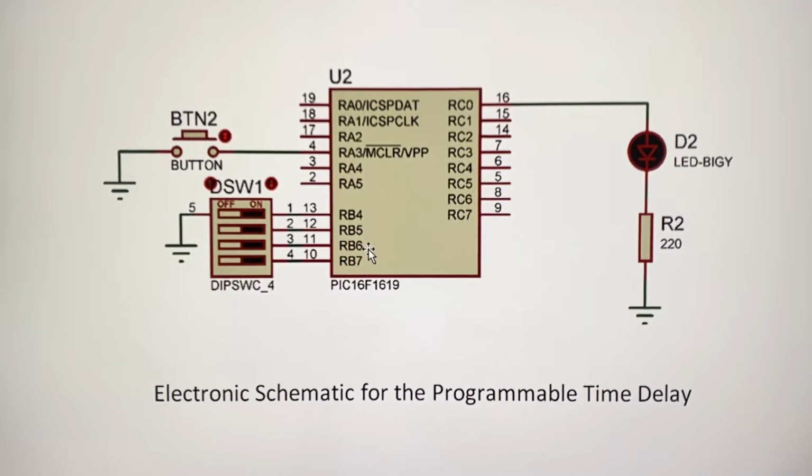So this is the range of this timer, which can operate within the range of 1 to 15 seconds. And we will use some of the previous software that we used to generate these 1 second pulses. When you press this push button, it'll start a sequence. If the code here is 0, there will be no output. If the code here in binary is different from 0, then you will see an output.